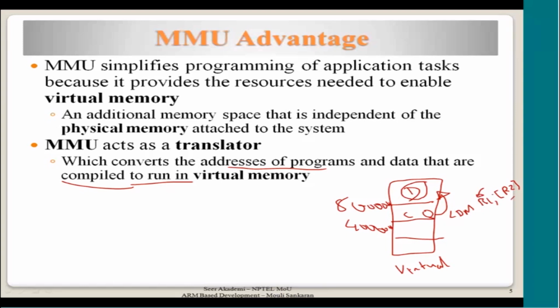Now what we need to know before we run this instruction is that R2 should have been loaded with the proper address, right? So I could have said move immediate, maybe 80,000. I am writing from top to bottom, bottom to top, but I think you will be able to read it.